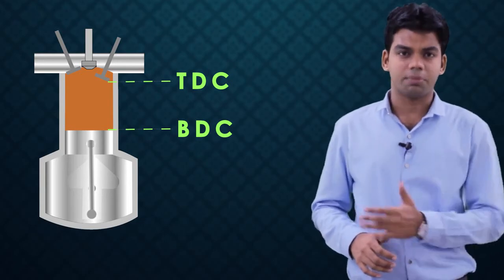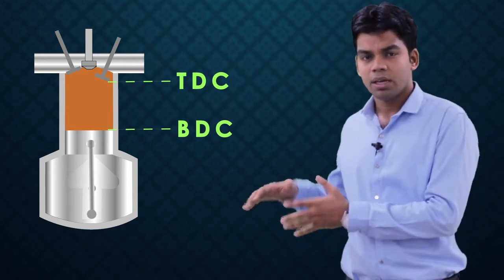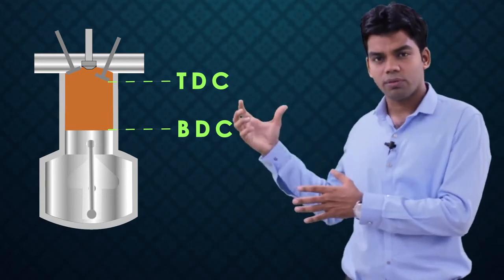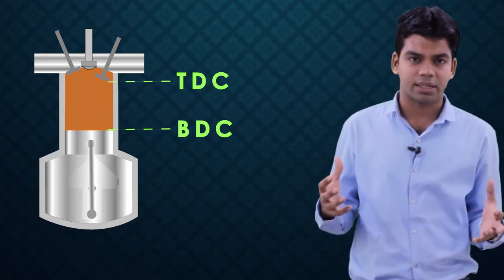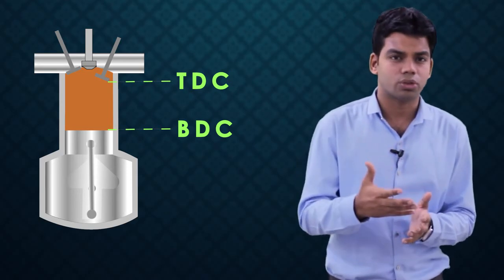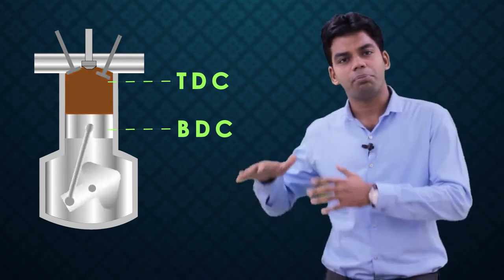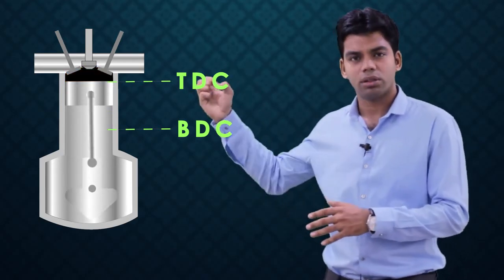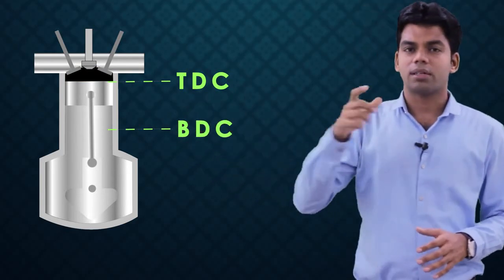Similarly, heat rejection is also at constant volume. Now what does this mean? This means the piston is at BDC, complete heat is rejected as the exhaust valve is open, and after that heat is rejected, we have the exhaust stroke, in which the piston moves from BDC to TDC driving all the flue gases outside. So these are two important things here. This is how the SI engine functions, and the cycle used in a spark ignition engine or petrol engine is called the Otto cycle.